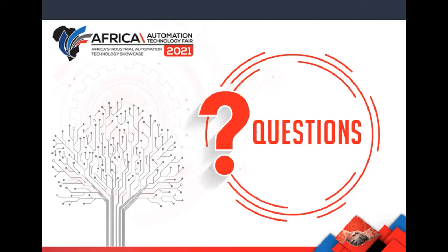And I think OPC definitely does have a space in building automation systems, because it can be used to share data across many different types of systems. It can probably be a common communication interface between different disparate systems. You could call it a bridge or a tunnel between those different systems. So OPC UA is definitely up there with MQTT as that common IoT type language, especially with the amount of flexibility and associated supporting data which you can use in OPC. Thanks so much for the question.